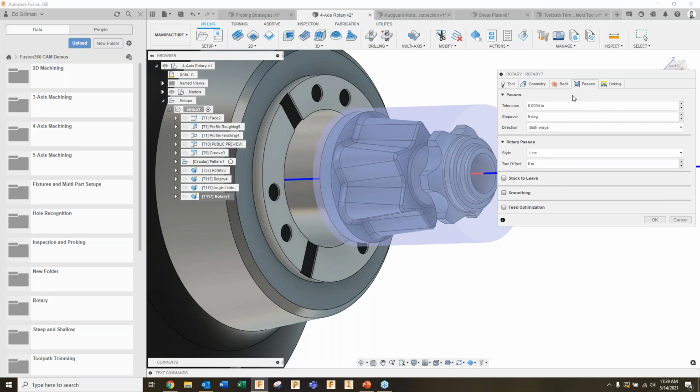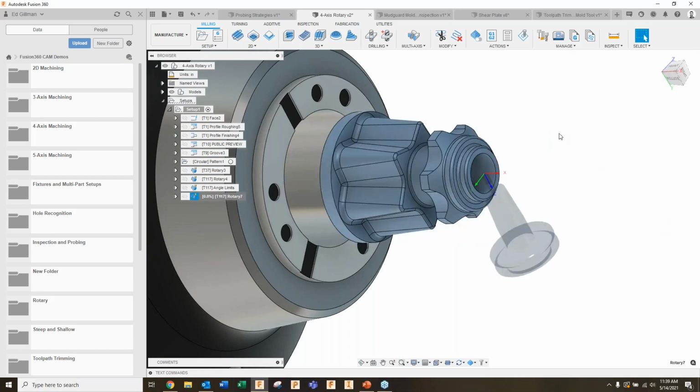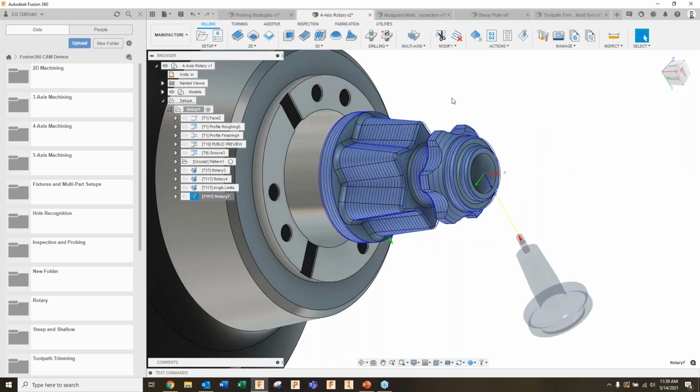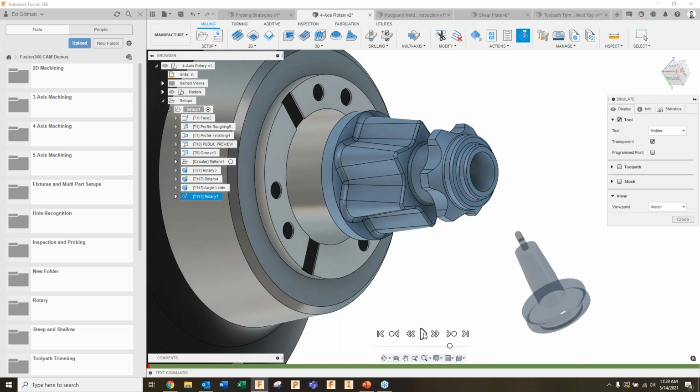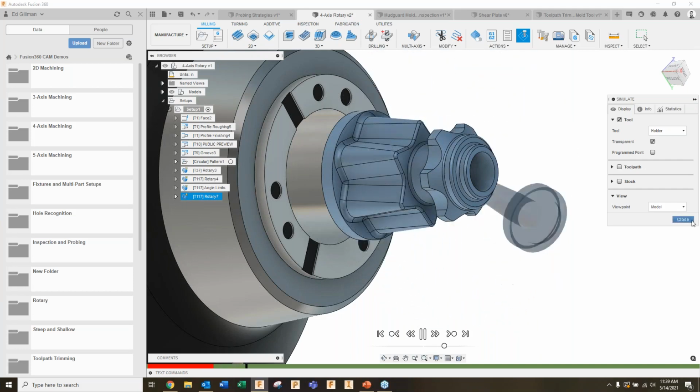And then lastly is the option to do circular. With circular, again, it's going to not link them together. So it's basically going to look similar to spiral, but it breaks it up into individual passes. So after each pass, it steps over. So it's going to run around, step over, and then run back around the other way. So it's not continuous. It does step over in between each pass, but this can work really well for these types of parts as well.